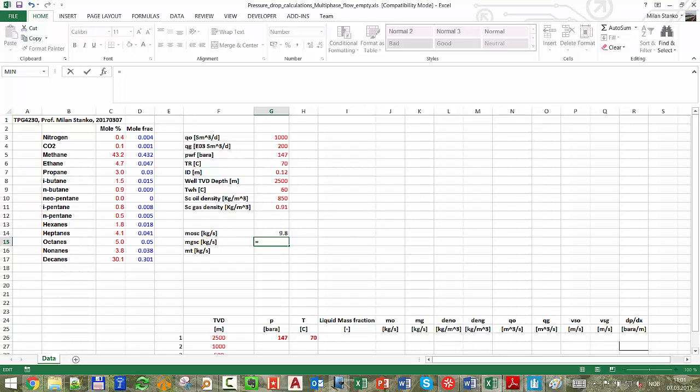And then I have the rate of gas times 1000. Remember here I have an e to the 3, times the density of the gas at standard conditions. Here nothing special is happening. I'm multiplying rate at standard condition and density at standard condition, divided by 24 times 3600, 2.1. That tells me that the total mass rate circulating through the wellbore is 11.9.